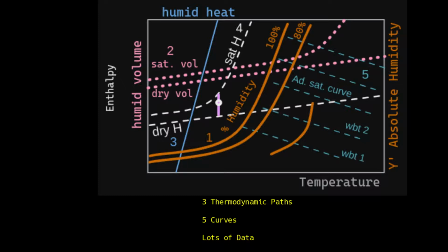If humidity y dash is known, the saturation temperature can be found by moving horizontally and then intersecting at the 100% saturated curve, and then moving vertically down to find the x value, which is the Ts. If humidity y dash is known, Cs, that is humid heat, can be found, and these humid heat values are on the top left x-axis. If dry bulb temperature and percentage saturation are known, humid volume and enthalpy can be found by interpolation in the vertical line segment, which is shown for the enthalpy curve in this chart.